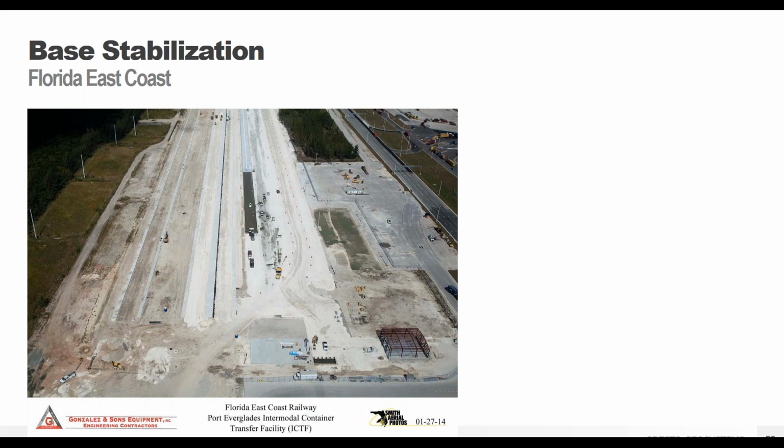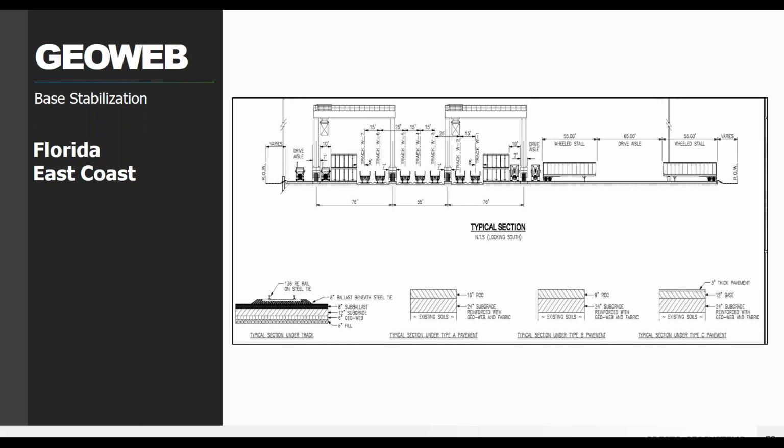And so, since this was a design build project, Presto Geosystems was asked to come and actually be part of the team to provide a new solution that would generate cost savings and still protect against those settlement concerns. So we were able to work with them for both of those pretty unique functions. And so the first feature was actually the ability to use inexpensive sand fill to replace expensive crushed limestone.